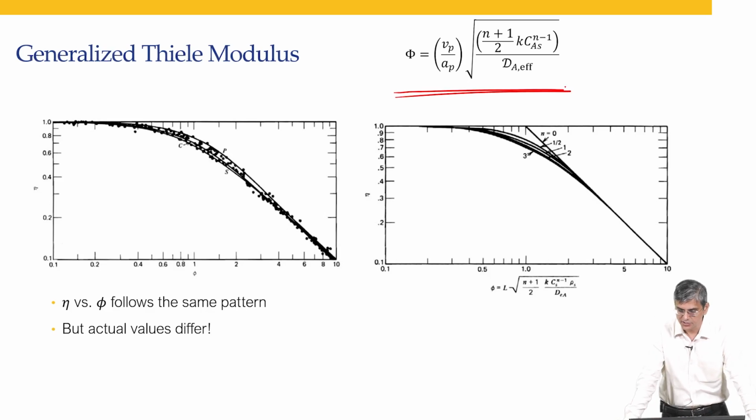This was the definition that they used. So, this would be applicable for any nth order reaction, and any dimension, any type of catalyst pellet. Is this accurate? No, it is approximate. But the beauty of this is that for any power law kinetics or any reasonably arbitrary size or shape of a pellet, this will still be applicable. If you have a very fractal pellet, or if the pellet is 3D printed to have funky shapes, yes, this is not going to be applicable.